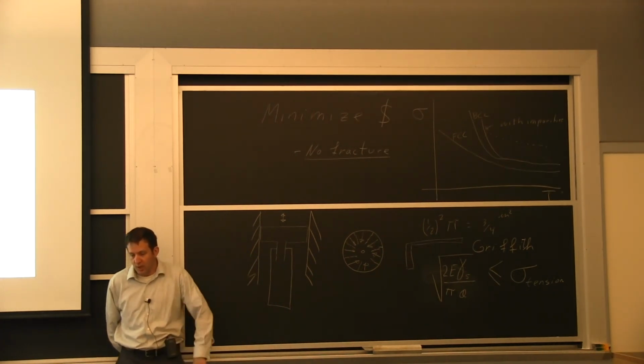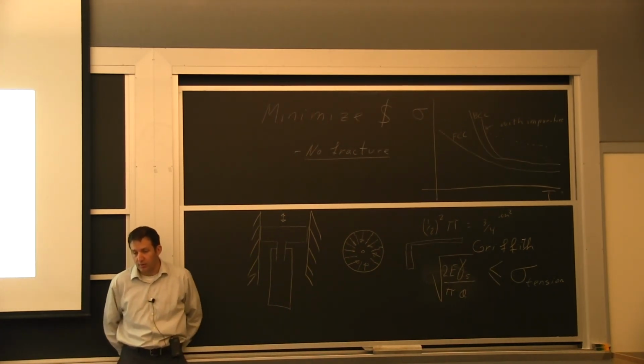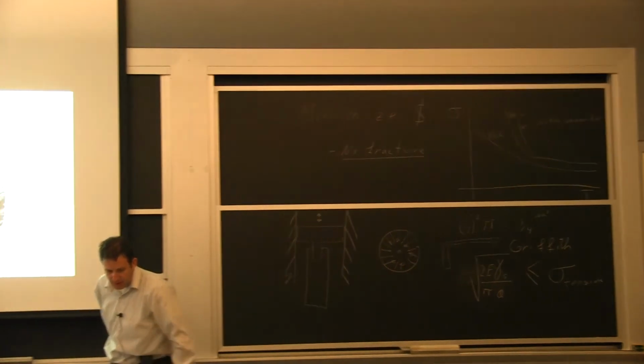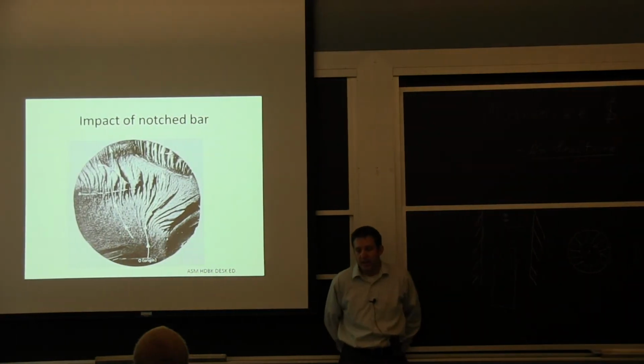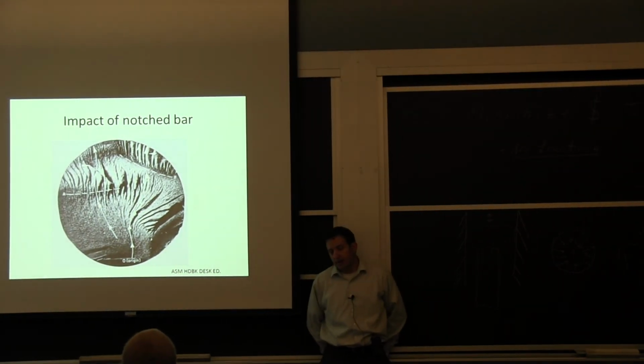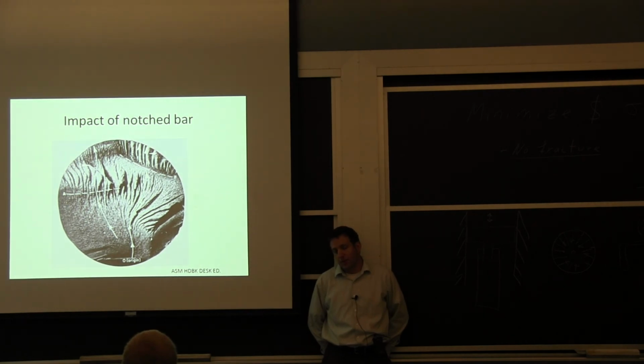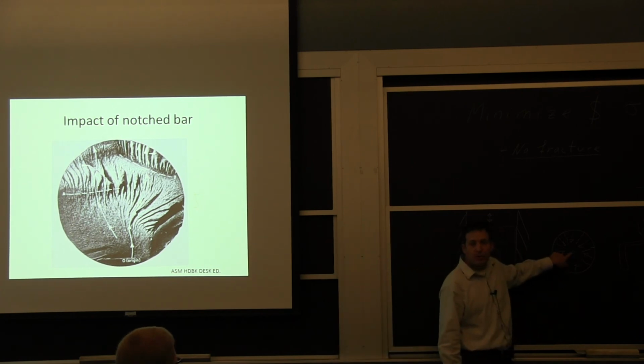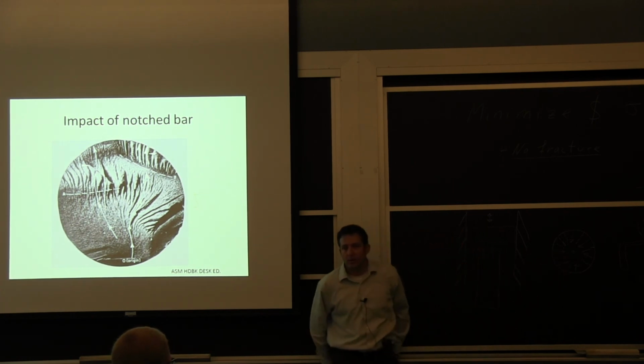Now, this example we have here is the crack stop. And that's where you see the little dotted line, or change in the way it's deforming. So these we call the crack arrest lines, and they run perpendicular. We only have them here in the middle in the example that I circulated.